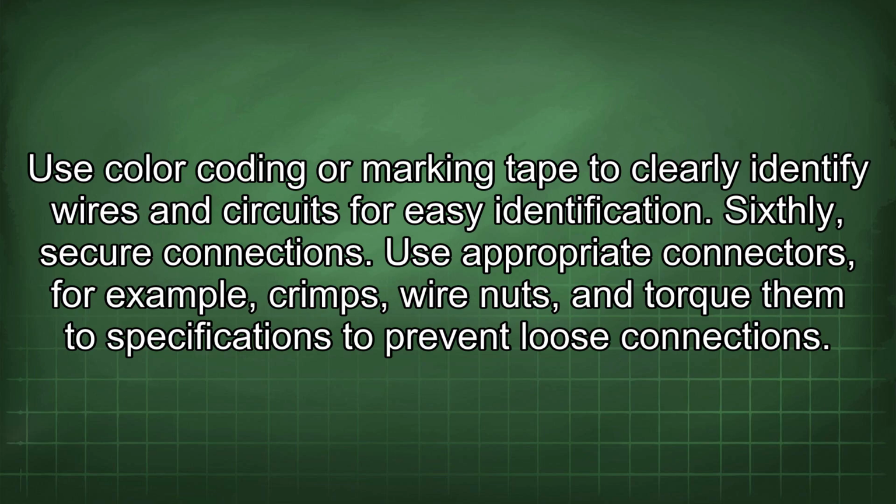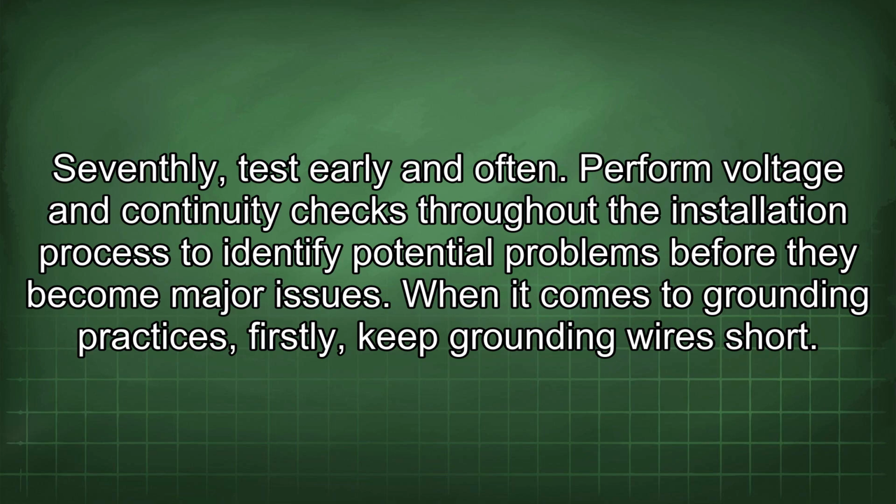Sixthly, secure connections. Use appropriate connectors, for example, crimps, wire nuts, and torque them to specifications to prevent loose connections. Seventhly, test early and often. Perform voltage and continuity checks throughout the installation process to identify potential problems before they become major issues.